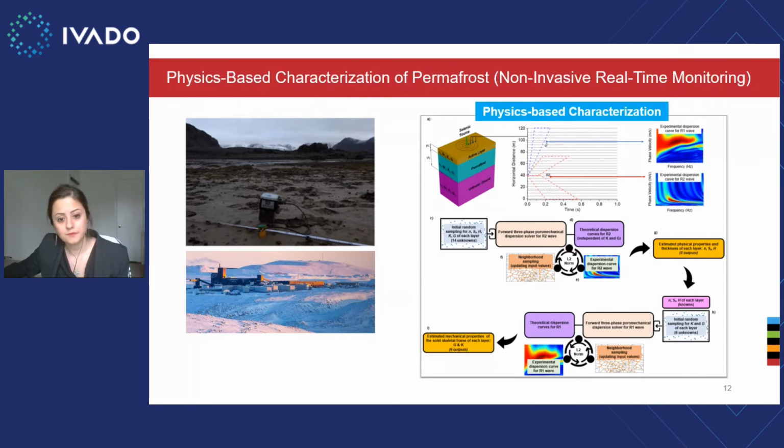Then what we actually developed is that we detect the presence of different surface waves which are each sensitive to a set of parameters. This is actually a huge contribution to the literature. This signal interpretation is very important for us. There are lots of mathematics behind that, but the purpose is through each signal we can detect a series of parameters. For example, ice content, unfrozen water content, and mechanical properties. Through mechanical properties, we can also detect if in the ground we have a layer which is sensitive to methane emission, greenhouse gas emissions. They are normally peat materials that through those mechanical properties and, for example, the stiffness of the layer that we can detect through this signal processing, we are able to detect these layers for more detailed analysis.